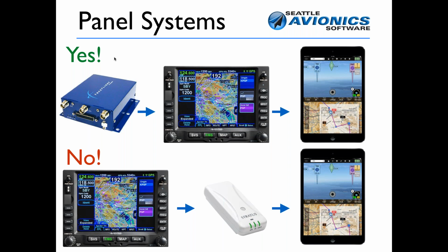It'll get position information from the Avidyne, and position information broadcast from the internal GPS on the Stratus or Stratux or whatever you have. So you get two different position signals, and that will drive FlyQ crazy.